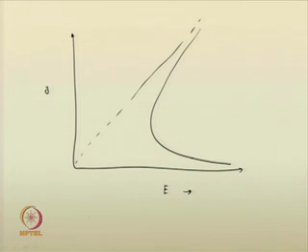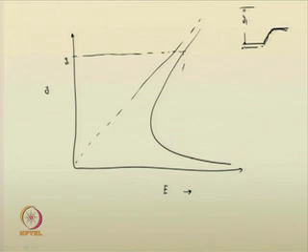So, for the given rectangular channel section, say like this, the bed elevation is increasing. Here the depth of flow is y 1. For the y 1 value, you evaluate the specific energy. You find the hump elevation del z.